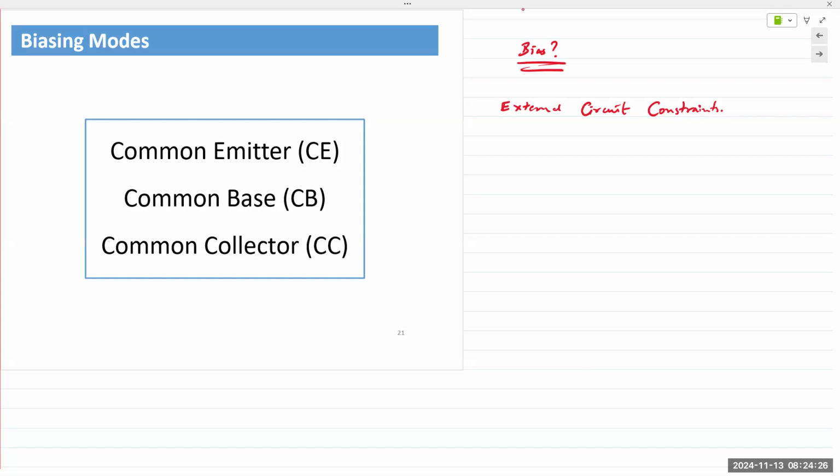Amplify it. Exactly. So this is something I always like to point out again and again: when we talk about op amps, we say an op amp has infinite gain. You have inverting and non-inverting configurations of op amps that can have gains of tens or hundreds, right? So if you apply a 1 volt signal, we'd expect a 100 volt output. But that's not true. Energy cannot be created out of thin air.